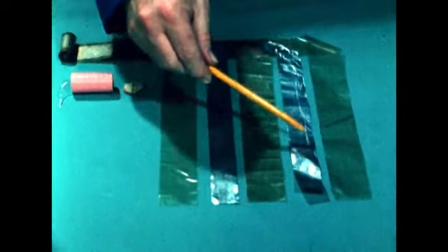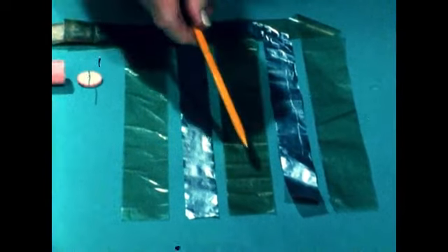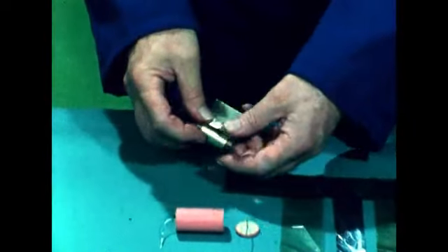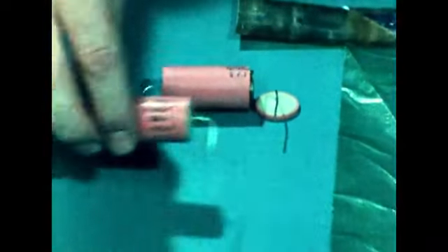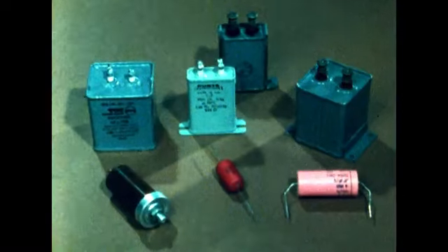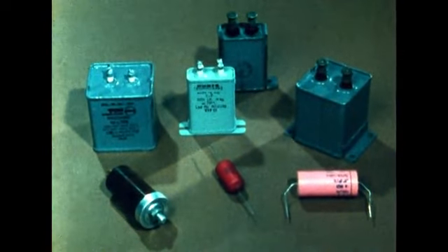If we take a capacitor to pieces, we find that it consists of two strips of metal foil with leads attached. These are the plates, with a strip of waxed paper between them to form the dielectric. Further strips of waxed paper inside and outside act as insulation. The whole thing is rolled up into a cartridge and sealed with wax into an outer case. Large paper capacitors are usually sealed into metal containers.